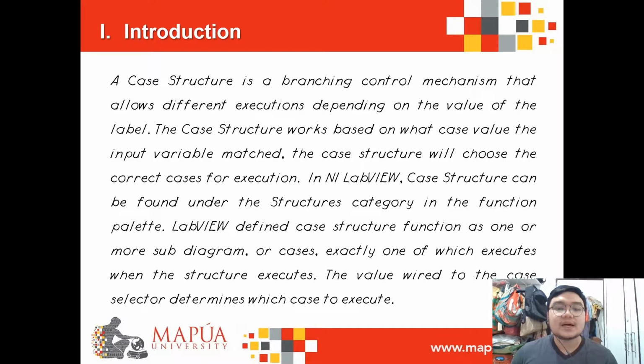In NI-LabVIEW, case structure can be found under the Structures category in the function palette. LabVIEW defined case structure function as one or more subdiagrams or cases, exactly one of which executes when the structure executes. The value wired to the case selector determines which case to execute.